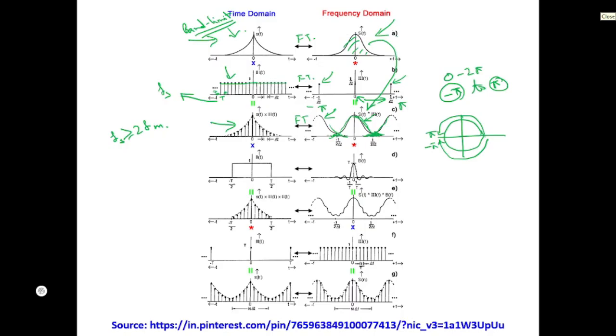So this phenomenon where a high frequency component mixes with a low frequency component is called aliasing. It happens when we do not follow the Nyquist criteria, that means f is greater than or equal to 2 fn. Okay. Now, if you see over here, what we have got is nothing but your discrete time